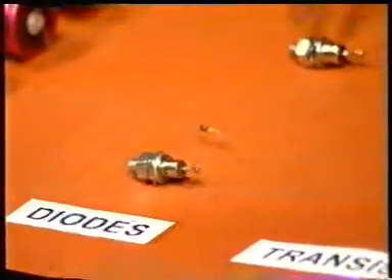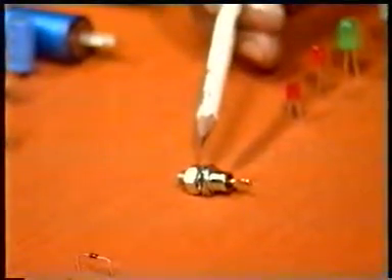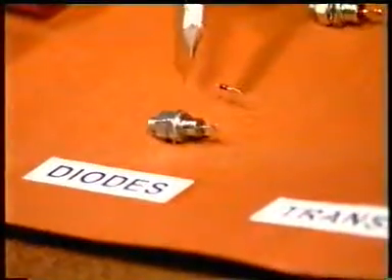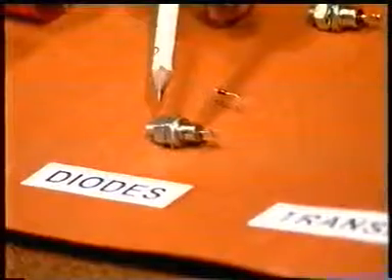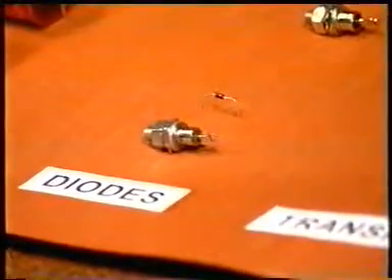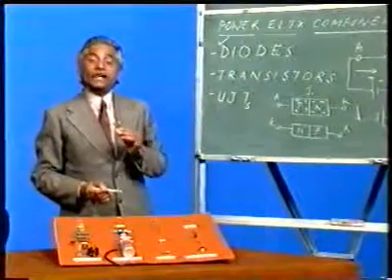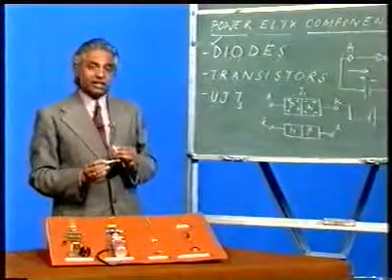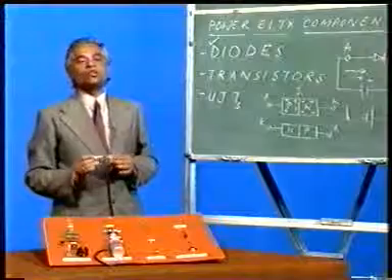The metallic diode, as you will see, is completely packed in a metal pack, and this has two terminals, one this, the other this. One of these two terminals will be anode, the other will be cathode. And this type of diode is also a metal type diode, but this is different. These two are known as Zener diodes. A Zener diode is a specific diode which, when it conducts, will give a constant voltage across it.